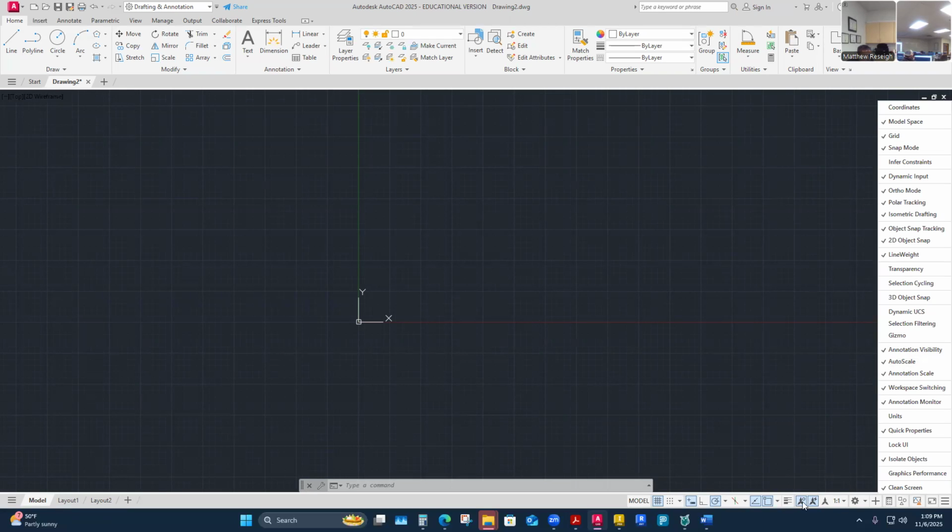Yeah. So mine are turned on because later after this class, I'll probably be doing drawings. What those are is automatic updates when I go from a model space that's in one-to-one and I go to a drawing that maybe is at a half scale, it's half size to be able to fit on my sheet. This thing will automatically do some of the scaling adjustments for my dimensions, my text. So that's what that is about. That's a good question though. Yeah, these are some of the AI automation that's in CAD.